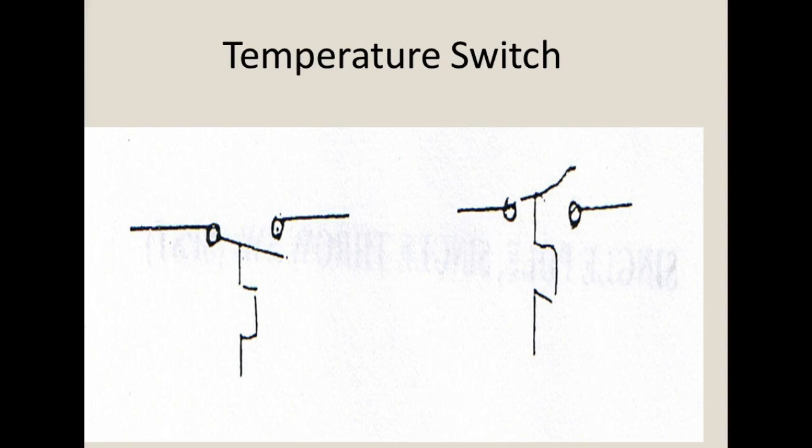I'm going to pass it around. That's a single throw, single pole switch. That's what we're looking at. It's a switch that's closable, right? I labeled it L because most of the time you use it for a light switch, although you could use it for anything as long as you didn't go over the voltage rating or amp draw that it could handle.